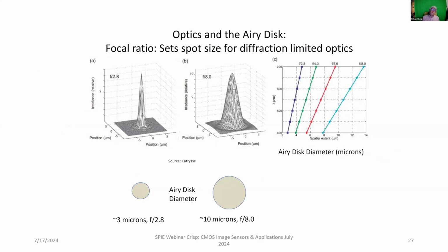Finally, one of the things that we care about is the optical characteristics. It turns out that light doesn't focus to a point. It actually focuses to what they call the diffraction limit. When you focus the light, you see this profile, if you will, of the light focus cone. There's something called the Airy disk, which is how small it will focus down at the bottom, and that's a function of the F number of the lens that's exposing it.